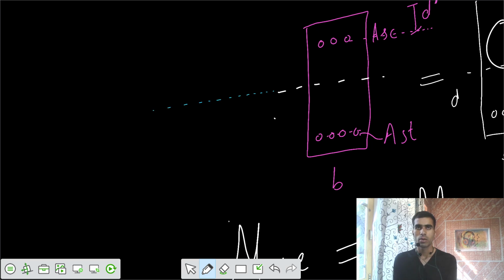What was assumption number 2? Assumption number 2 was that the strain at the topmost extreme compression fiber is 0.0035 and it goes to 0 at the neutral axis. In the doubly reinforced beam we are not changing the neutral axis. We are keeping the neutral axis as it is.